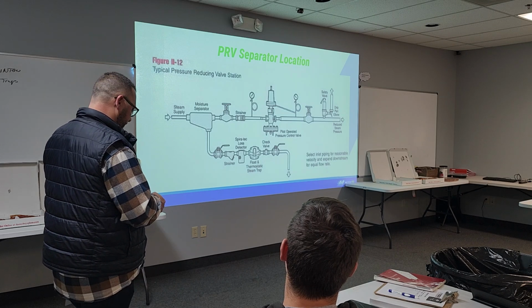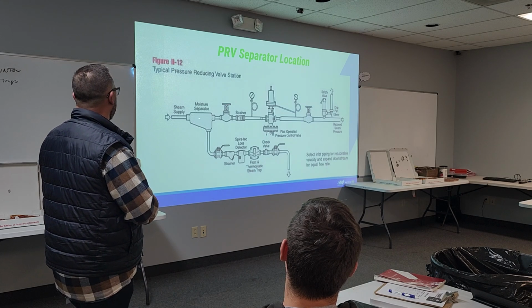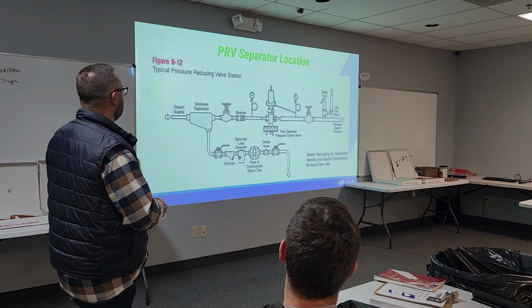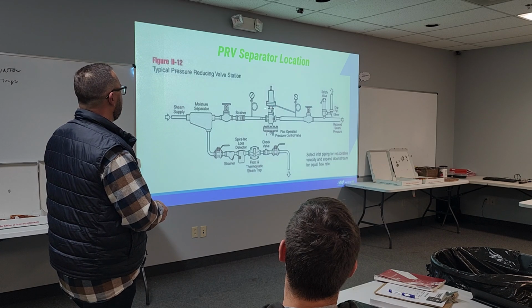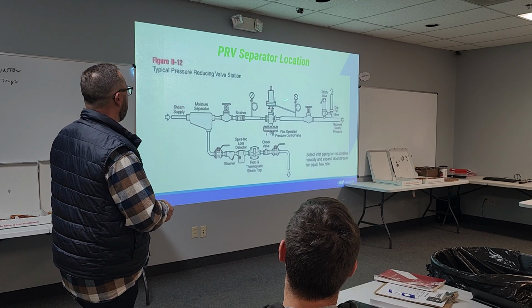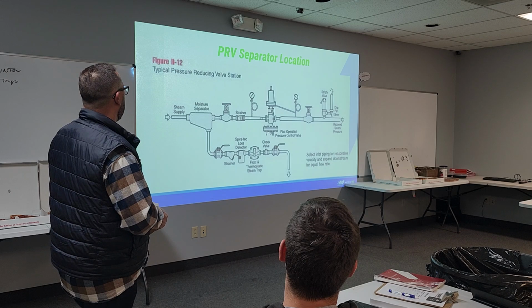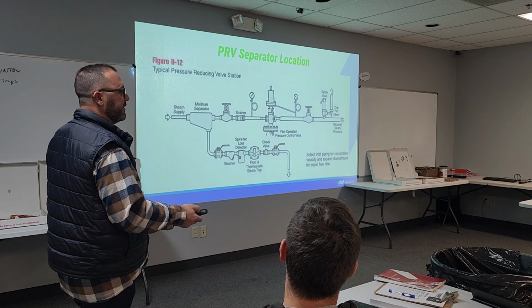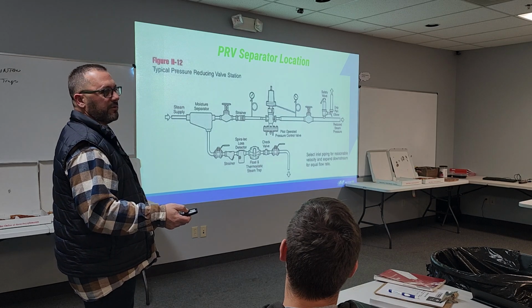Typical PRV, again, we've got our moisture separator, our strainer on its side, gauges with pigtails, and this downstream sensing line that is angled down. If it were angled the other way, we'd have condensate on our pilot. And the news here is that these PRVs are not line sized. The outlet, what did we say about steam? It's compressible.